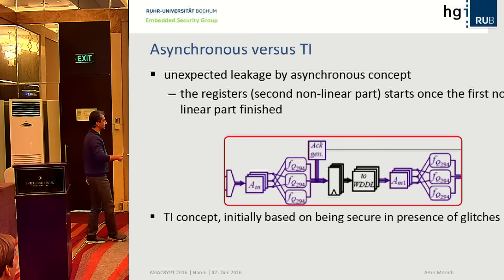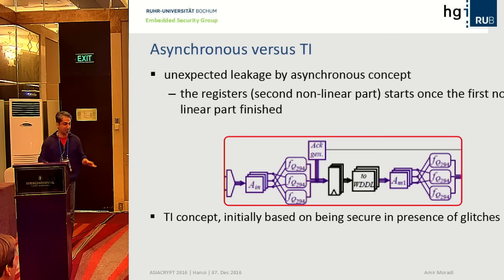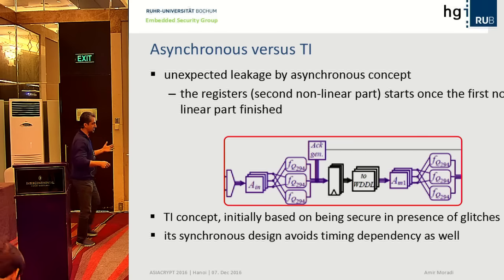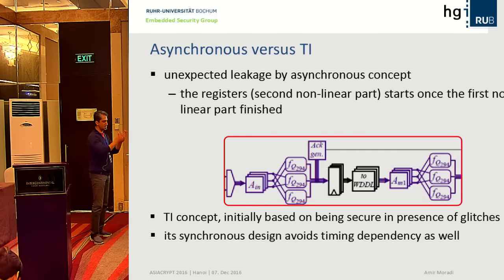And the good thing is, if you come back to the TI concept, TI was initially proposed to be secure in the presence of glitches. But actually, it also has a synchronous design which avoids this timing dependency. It means that, unintentionally, the design of TI was synchronizing all these stages and made the second stage start completely independent of the first stage.